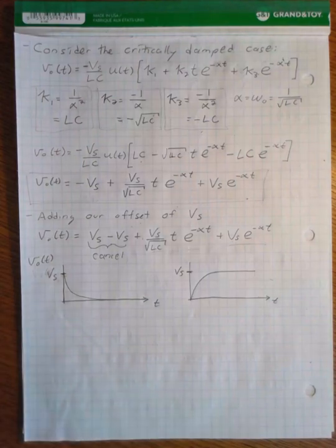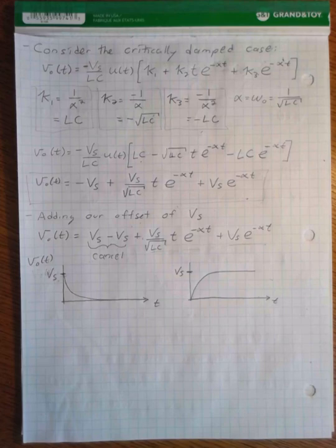This is consistent with the first order RL and RC circuits we looked at. The transient response was basically the same. The only difference is that in the step response, we start at 0 and converge to our source voltage, and in the source-free response, we start at the source voltage and converge back down to 0. So this is what we would expect.